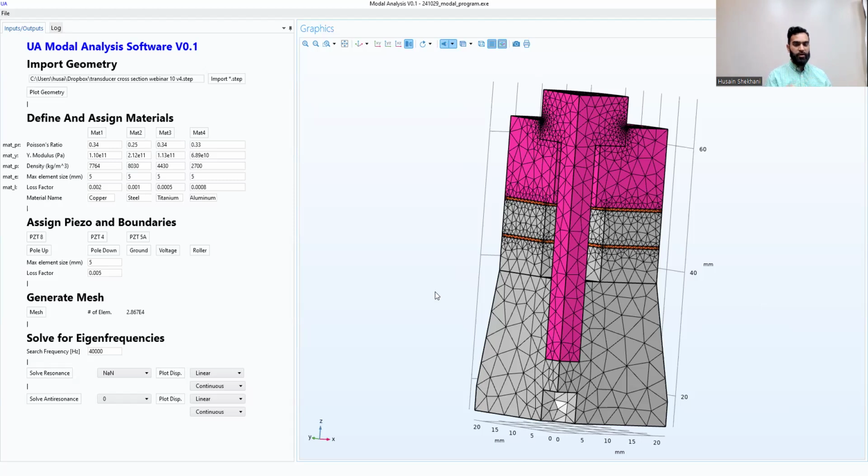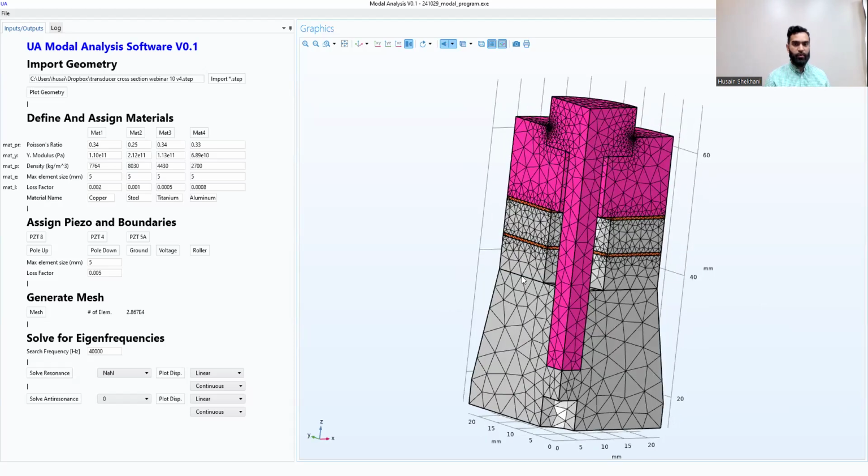So addressing each of those one at a time, in reality, the amount that the geometry will change due to preload is very small, so it's negligible. The next part is in reality we have changing of interface acoustic properties of a wave traveling through an interface. When we preload it and the two components are more squished together, their faces become more conforming to each other. That's not something that we represent in finite element analysis in almost all cases. It's too much of a detail. We're going to lump that in somewhere else. We're not going to look for that level of detail in our analyses.